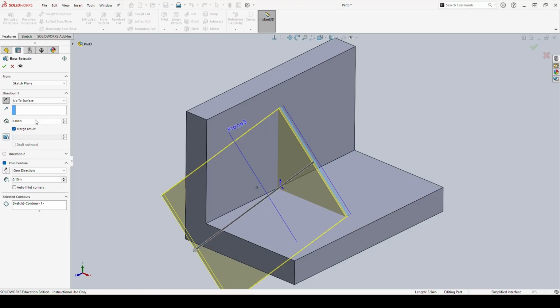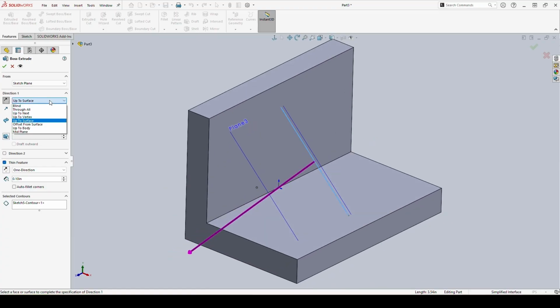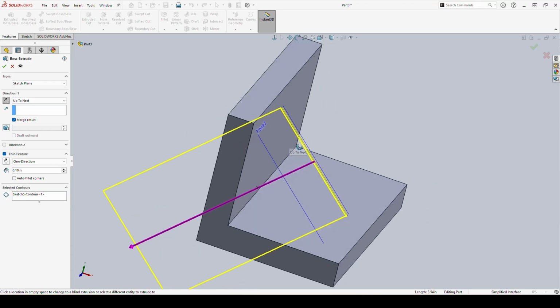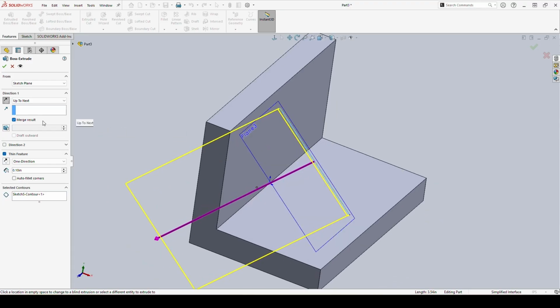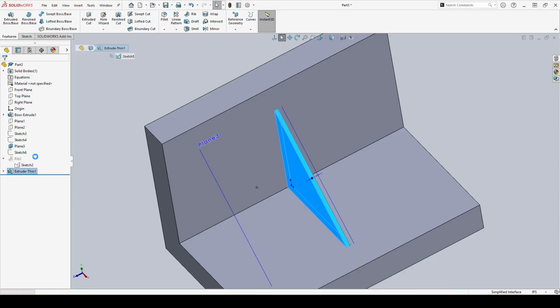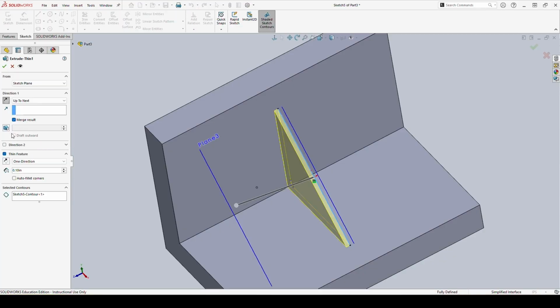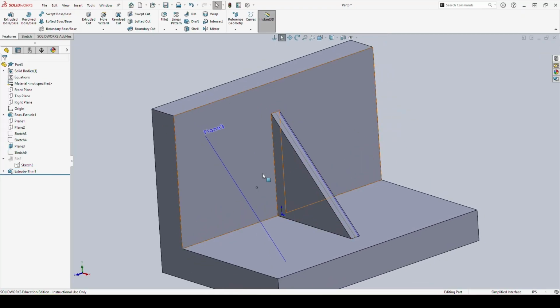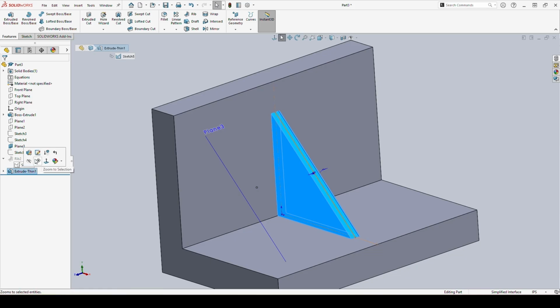So what I'm doing is I'm doing my thin feature extrude on this line up to next, so it's going to be where it collides with the wall, and you will see that this is exactly the same rib created, other than I appear to not have put in the right thickness for this, switching it to midplane, but either way, this is exactly the same rib that we are otherwise creating.